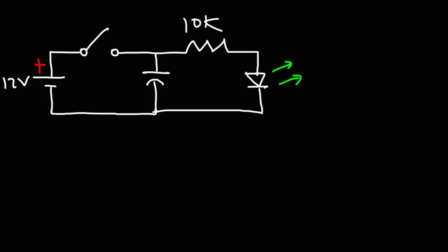And we're going to use a capacitor that can store a relatively large amount of energy. We're going to use a 16 volt 4700 microfarad capacitor. So when dealing with electrolytic capacitors, these are polarized capacitors. This is the positive plate, this is the negative plate. Two important things you need to look at are the maximum voltage rating of a capacitor and the capacitance.